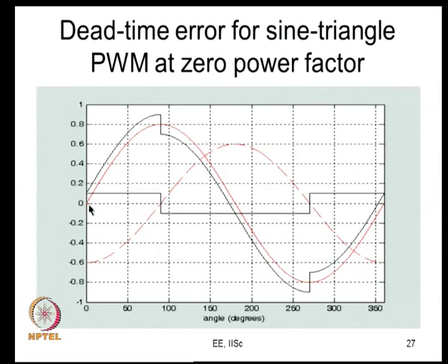Now, this average pole voltage, what happens? There is an error on top of it. So, rather than being the sinusoid, there is something added here. Again, this negative number is added here. So, it comes like this. So, this is your average pole voltage now. So, your VRO average is not as sinusoidal as it is expected to be in the ideal situation. It is sinusoid with some square wave added to that.